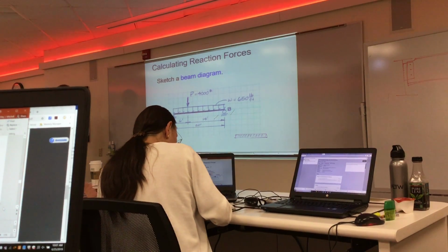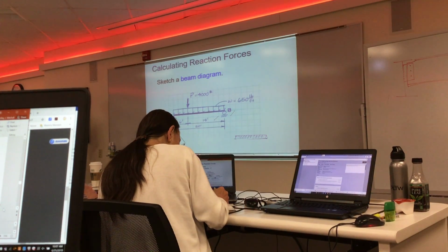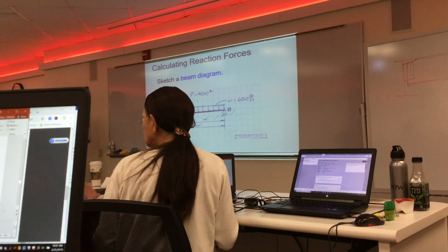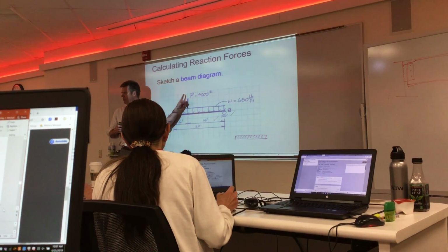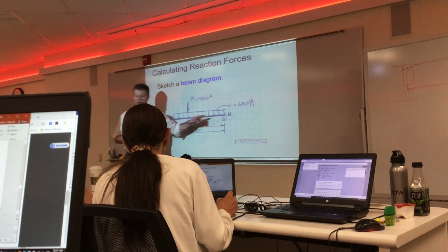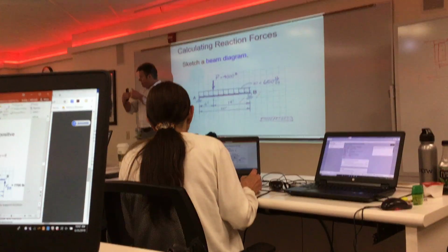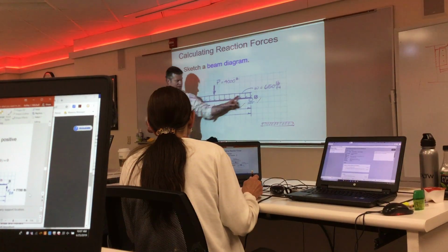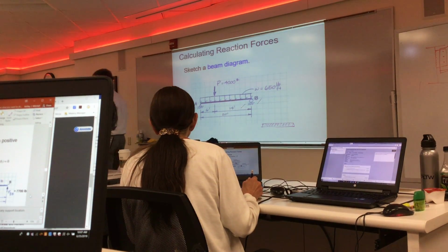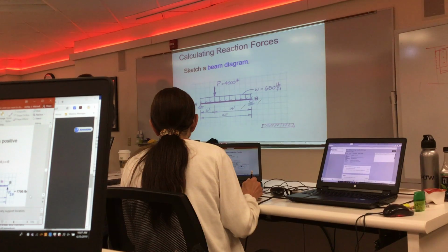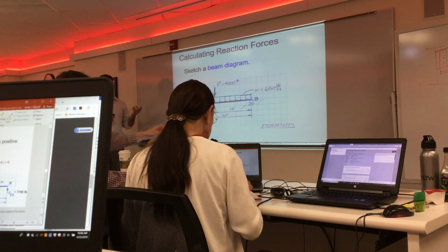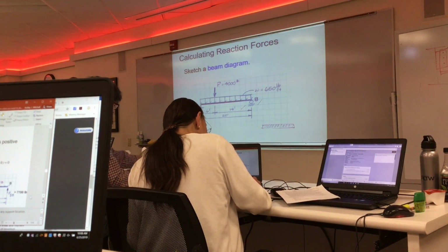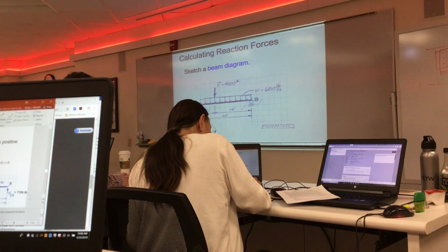Would it include the weight of the beam? Most likely, yes. And then possibly something else. So when we had our previous PowerPoint, we had a dead load of 40 pounds a square foot and a live load of 100. And then we calculated that times the 6'8", remember that calculation? That's what that uniform load represents, with a different number, but it's dead and live. Yeah, it's dead and live in this case. Beam's part of the dead.